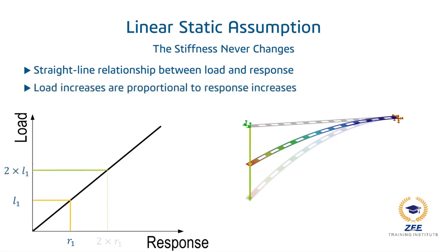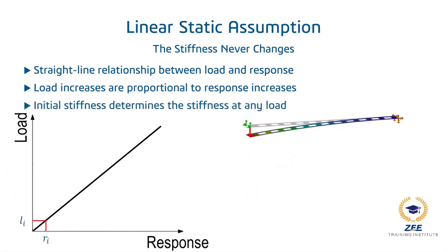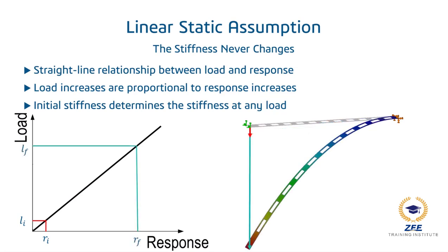If the load doubles, the results double too. This assumption forms the basis for how linear studies solve problems. When these studies solve, the software determines the structural response based on the initial stiffness, which never changes, and then applies the whole load in one step.